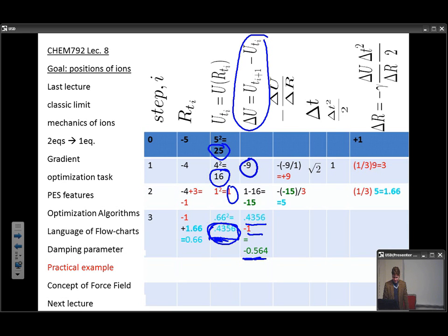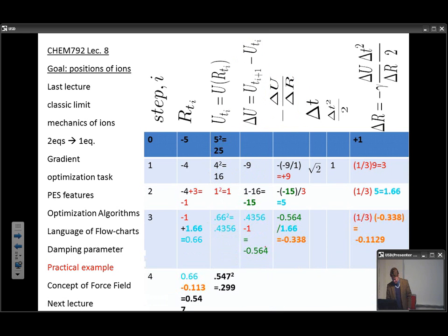So the convergence criterion was minus 9, then it went minus 15, then it goes to a much smaller value. So later we will observe how the computer is doing it, and when those convergence criteria get smaller and smaller, it is a good sign, meaning that probably we are using the right code, or the right setup of the code. Okay, now let's use this information to find the ratio and proceed with gradient. So this 0.5 divided by this increment will be the gradient.